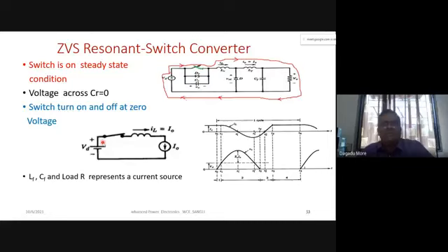Okay, the equivalent circuit we have shown here. The switch is on, and current will pass through LR, LF to the load, and return back. We have marked this path of current in red. From the positive of the DC supply to the switch, through LR, through LF, to the load resistance, and it comes back. This is the operation when the switch is on under steady state.